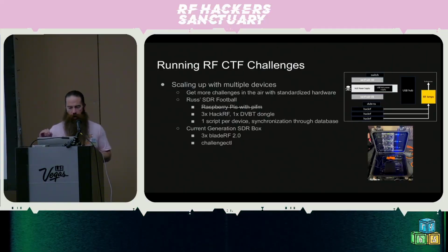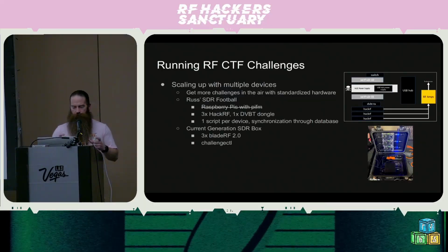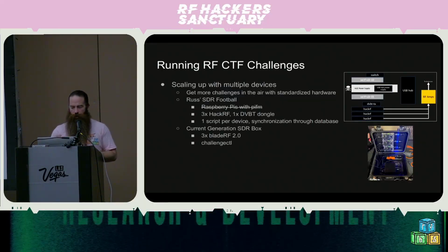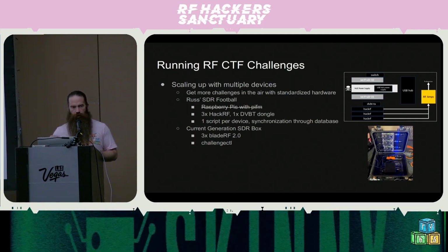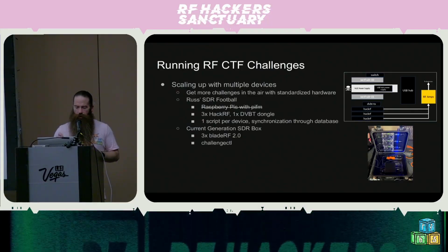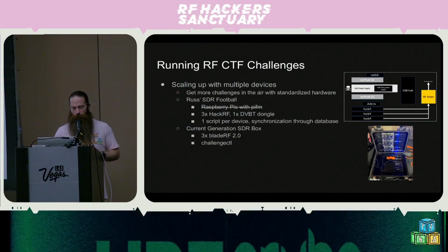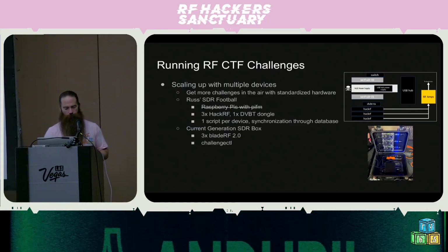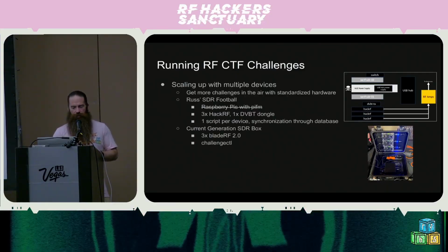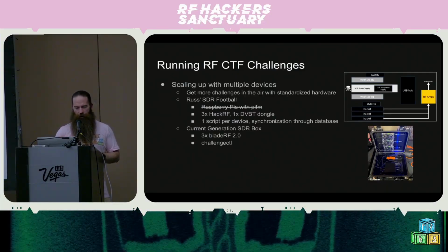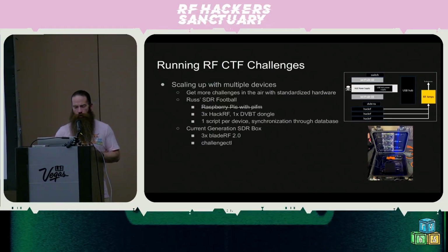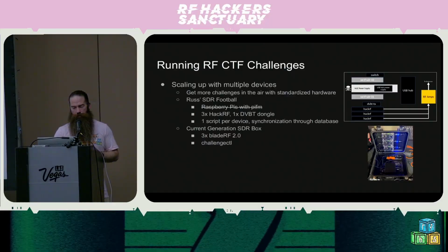The diagram up in the top right is essentially a functional diagram of the original Software Defined Radio football. There were a couple of Raspberry Pis controlling a few HackRFs, and then those going out to a couple of amplifiers. There was also a DVB-T dongle. That's some of that specialized hardware I mentioned before. From what I remember about running challenges on this, there was essentially one script per device per HackRF, and then there was synchronization happening through a database that was on one of those two Pis.